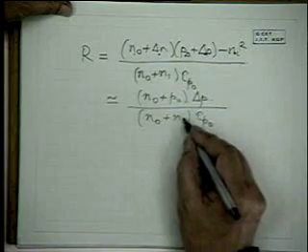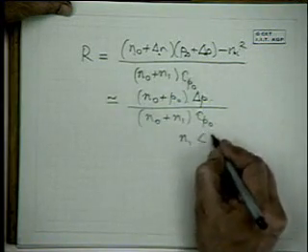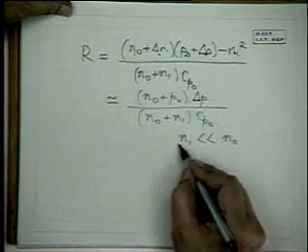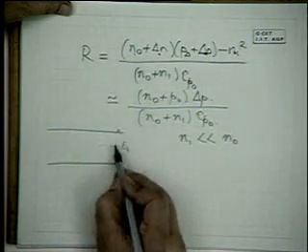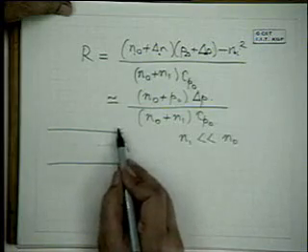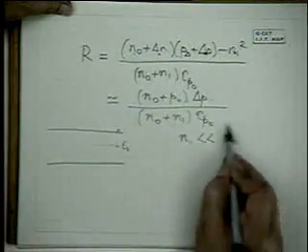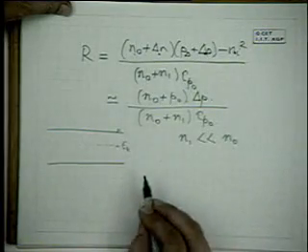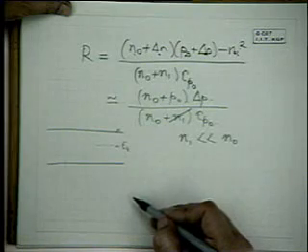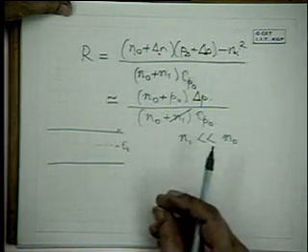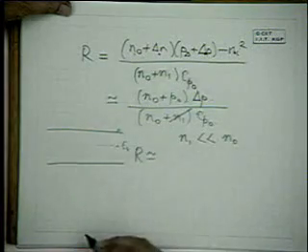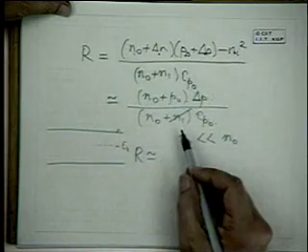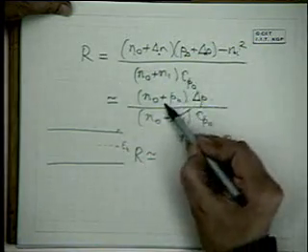now we assume that n1 is much less than n0. Why? Because n1 is the concentration when the Fermi level is at the trap. The trap is fairly low in. The trap is somewhere here. Obviously, the n1 is the concentration in the conduction band with the Fermi level here, which is negligible compared with n0. So we have the condition if we neglect that, then we have, and for an n-type semiconductor we've assumed that n0 is much greater than p0, so this is also negligible.